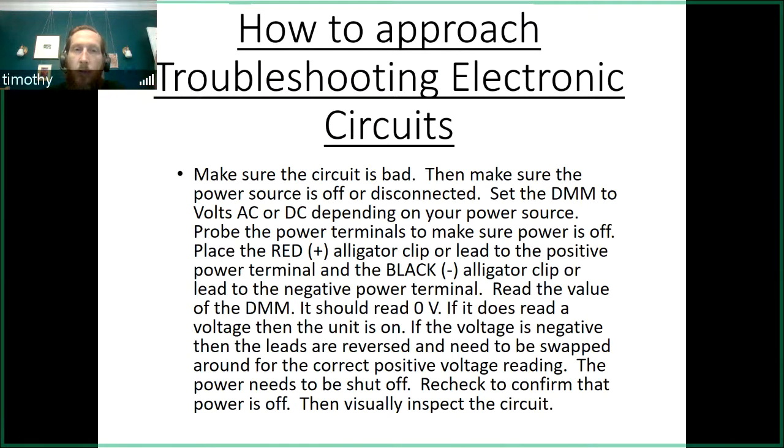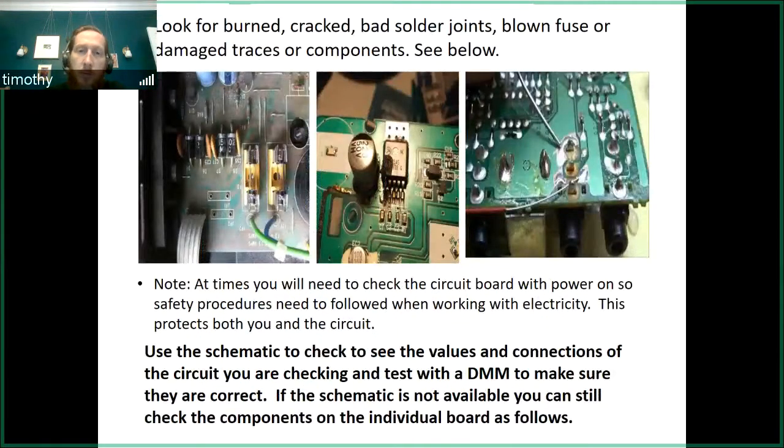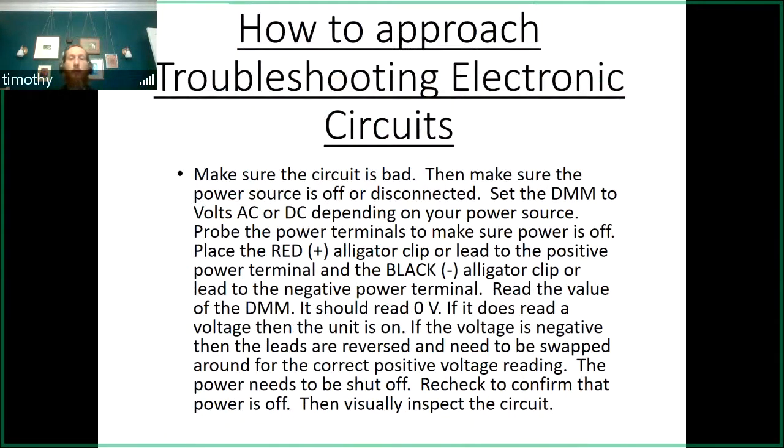But one of the things that you want to do, I'll go over this a little bit. When you first get your PCB, you want to take it and populate it. So you'll solder on all your components. Once you've soldered on all your components, then you want to take your digital multimeter and check your PCB before you ever apply power. So check your voltage rails, make sure they're not shorted to ground. Check the different leads of your ICs and make sure that when you soldered your ICs on, you didn't create a solder bridge between them.